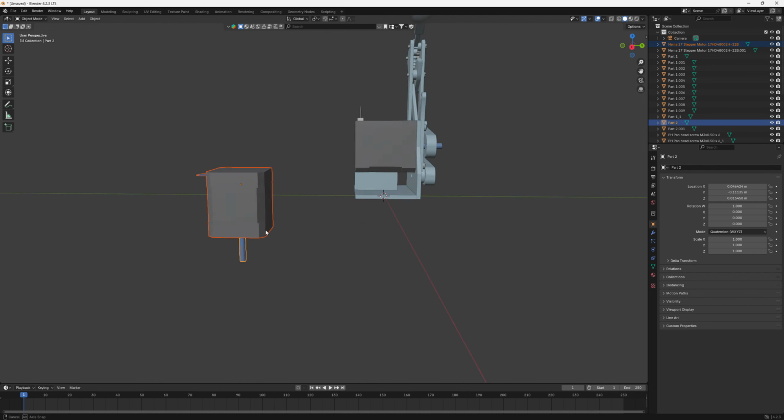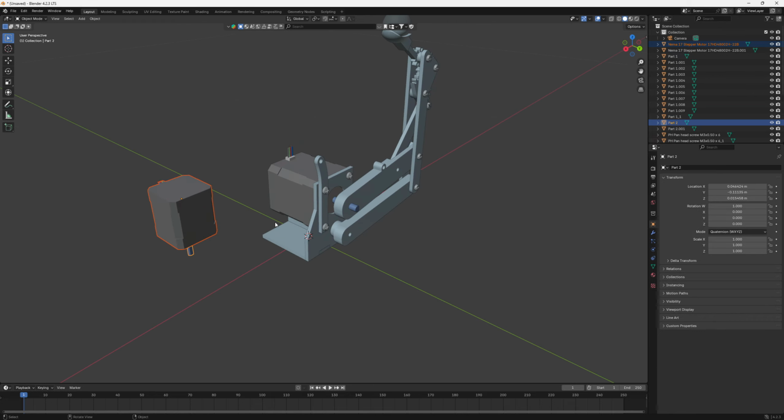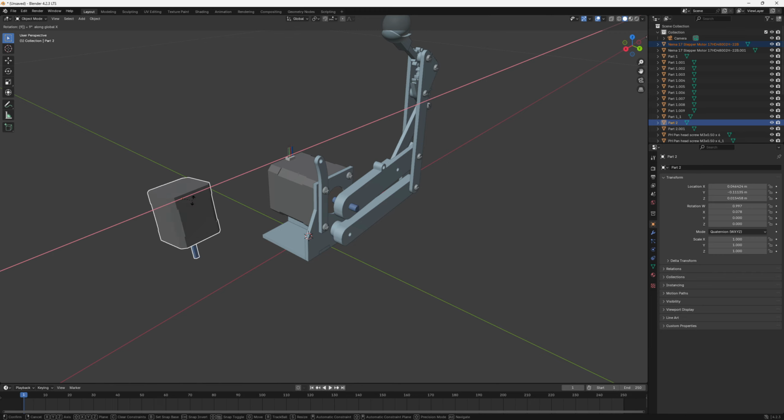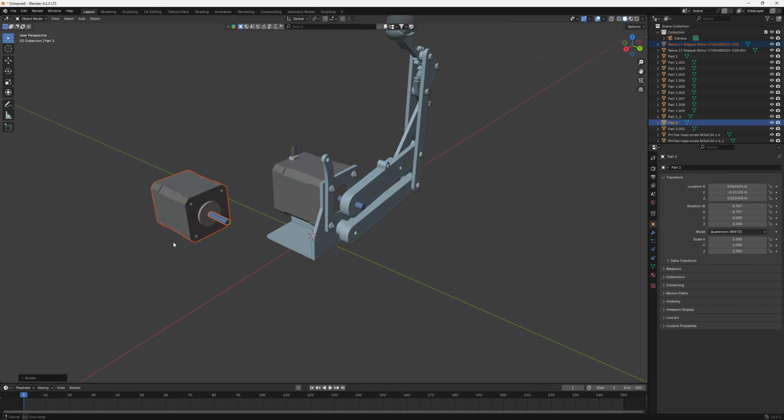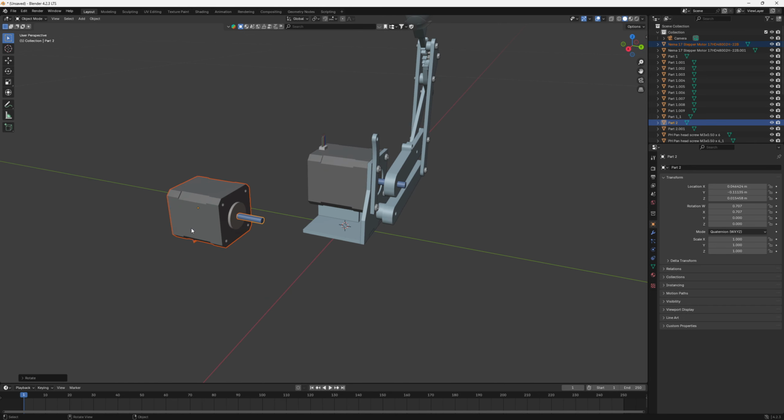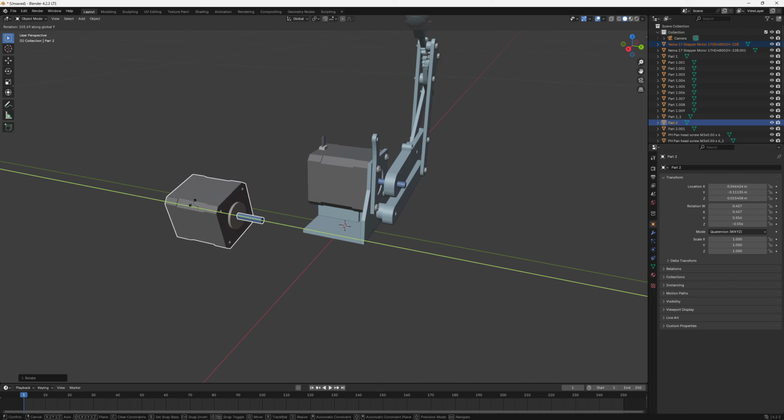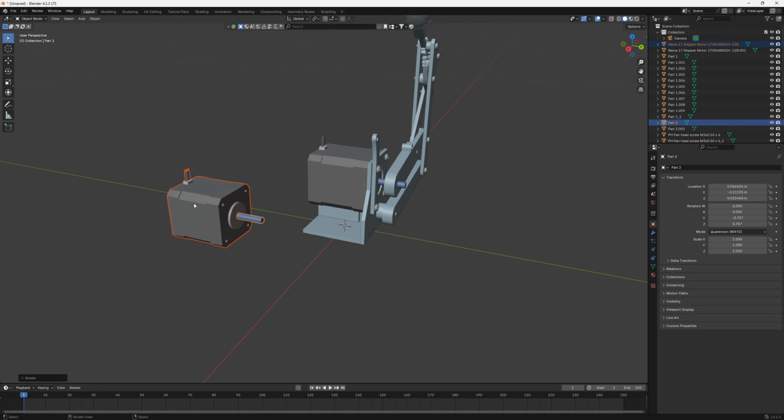Now, the only reason I brought that one in was to show you how the Part Studios work. We could rotate that around, and then we can use numbers on our keyboard to rotate it. So I've clicked on the x-axis and rotated it by 90 degrees by pressing 90 on the keyboard. And then I can rotate it by my y-axis, which is this one, and I could go by 180 to have these wires vertically upright.